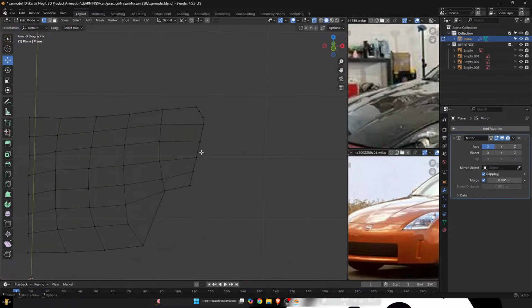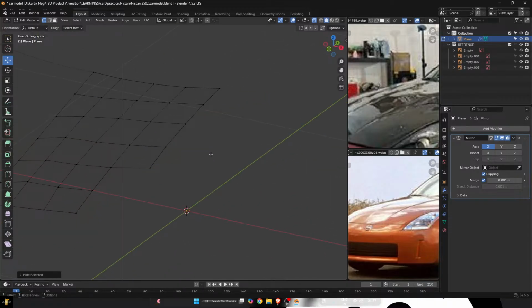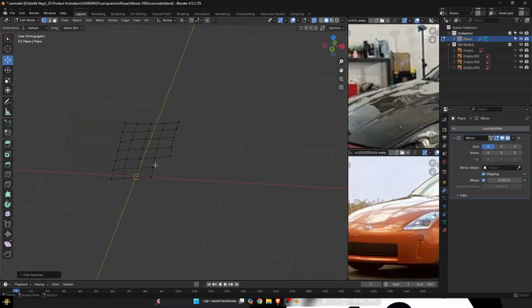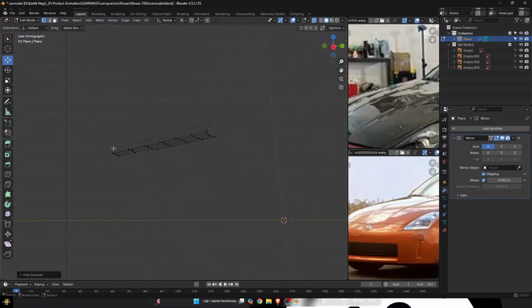To see over here, this is already aligned, right? And these are the edges which are making hindrance. So what we are going to do is Alt click on this one, so the edges or the vertices will be selected. Alt left click and Shift Alt left click and Shift Alt left click. Just deselect by Control box and H to hide. We are left with those which we really want to settle down.